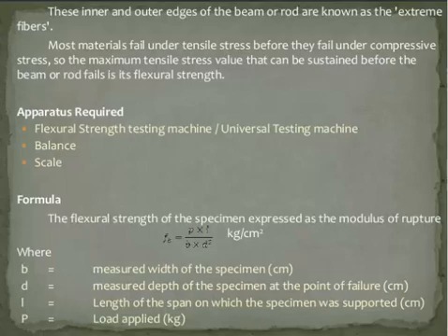So depending upon the type of machinery, the manufacturing company, the capability of the machine may vary from category to category. Then the other apparatus or equipment used for the flexural strength test are steel or cast iron or other non-absorbent material molds having a size of 150 mm by 150 mm by 750 mm.